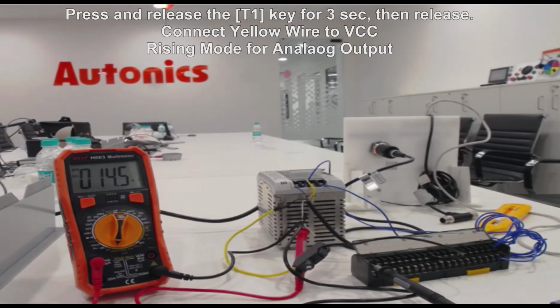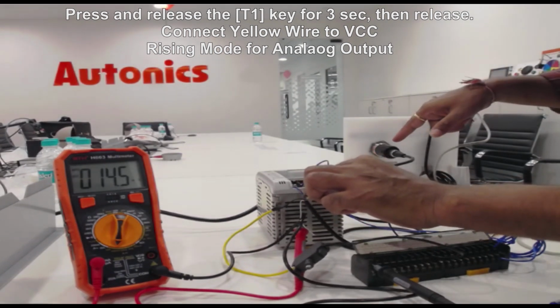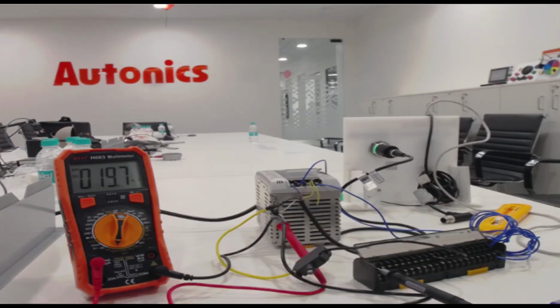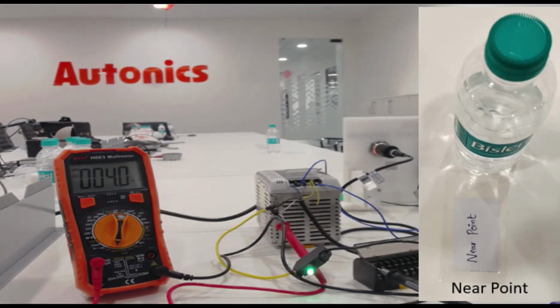Now I need to make sure, do I want to have a rising edge for the analog output or the falling edge? I want rising edge, so I need to press T1 key for 3 seconds. So connecting to VCC, 1, 2, 3. Okay, so the teaching process has been completed. Now we can see at the far point it is giving us 20 milliamps. If I keep the object at the near point, it is giving me 4 milliamps.